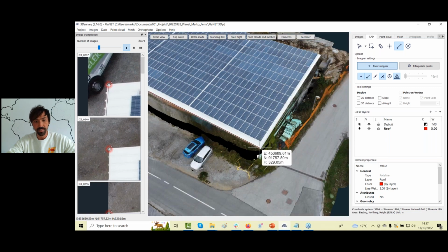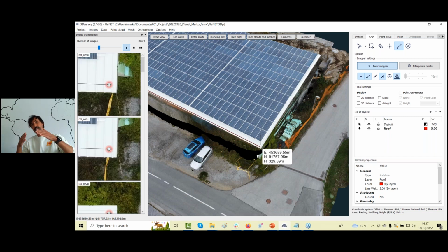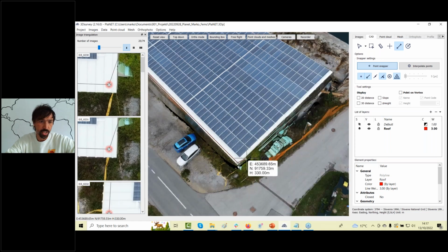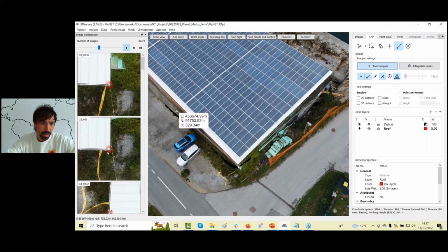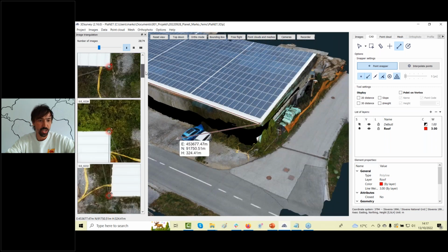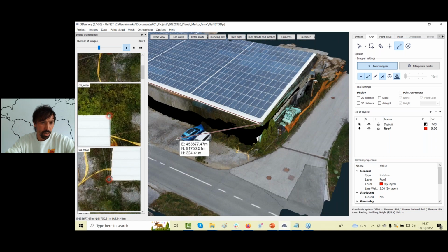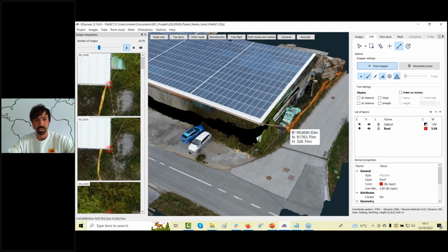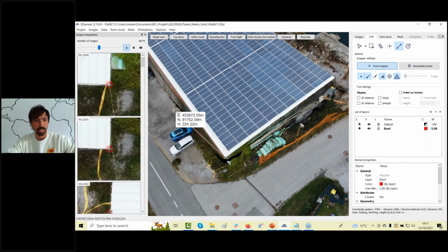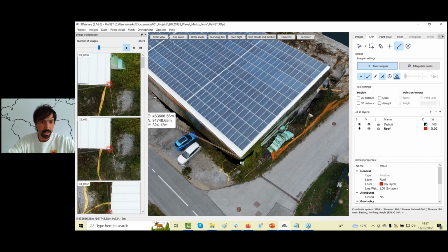Also, in case you have bad models, where the corners are not nicely designed in the model, or if the point cloud is not perfect, you can now accurately draw with the help of image support. So again, I click really quickly on the 3D model. Here I will improve the position on 2 images, and this is more than enough for accurate 3D position recalculation. Then, sorry, let's delete the last point with the delete button.